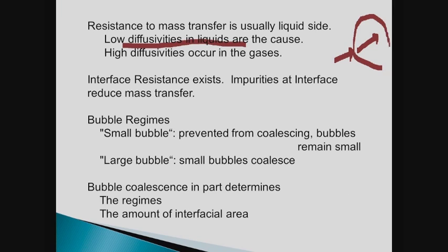The concentration in here is fairly constant across the bubble, whereas the concentration across the liquid side to the interface is quite steep. Most of the resistance to mass transfer is liquid side.